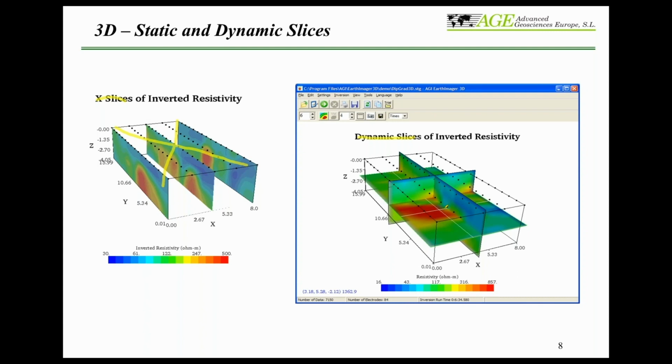You can locate exactly and highlight your anomaly, and just like here, you can see white lines. When you push the left mouse button, it corresponds to this point over here, and it will show you the coordinate of this point and the resistivity value. So especially when you highlight your anomaly, you want to give your drilling locations. What you're looking for, where you have to drill, will be your drilling coordinates over here, and then the resistivity corresponding to that anomaly.